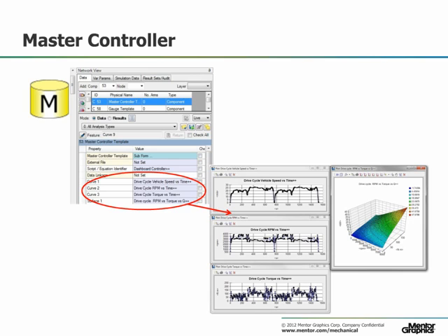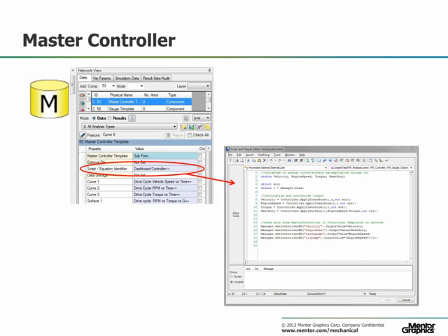As seen here, this data could include vehicle velocity versus time, which will affect the airside flow, engine rotational speed versus time, which will affect water pump rotation, oil pump rotation, as well as the engine heat load, engine torque versus time, which will also affect the thermal load of the engine, and finally the engine heat rejection as a function of both engine torque and engine rotational speed.